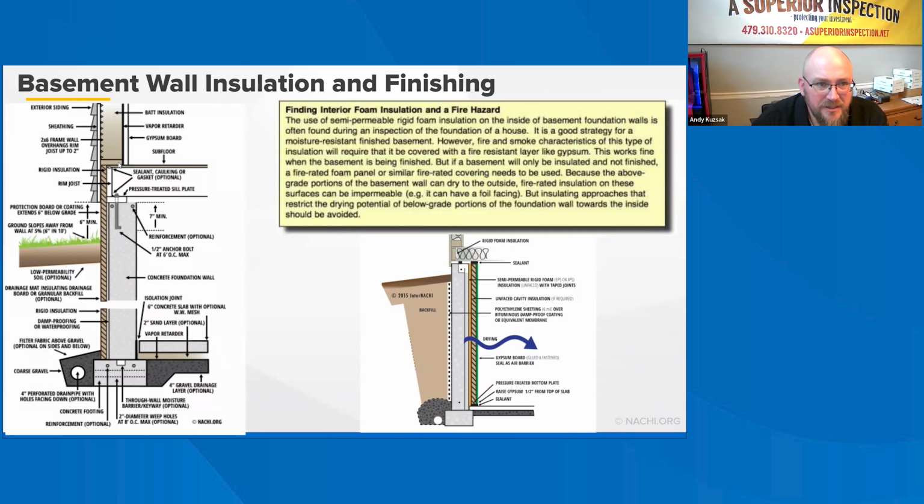See the rigid insulation and the sill plate is overhanging, so that it creates a continuous plane and the water and the wall cladding can correctly shed water away from the house. We find problems with this all the time in my area. A lot of times this is not pushed out, and so the siding terminates at the sill plate, and oftentimes you can see the gap between the sill plate and the exterior rigid insulation. Often, you might have to look up a little bit, but it's still visible, which it should not be.